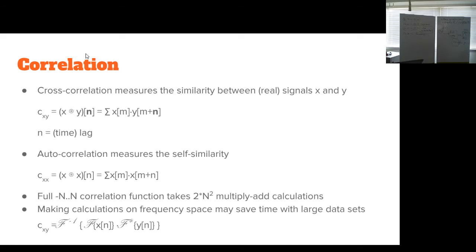Then what you need to do is calculate the cross-correlation. At some time difference you have a correlation peak, meaning you have the same signals with a time difference, matching the phase at some point. Otherwise it's random, meaning it does not correlate. Measuring that peak, you find out the distance difference, which is halfway, and so you can find out that distance.